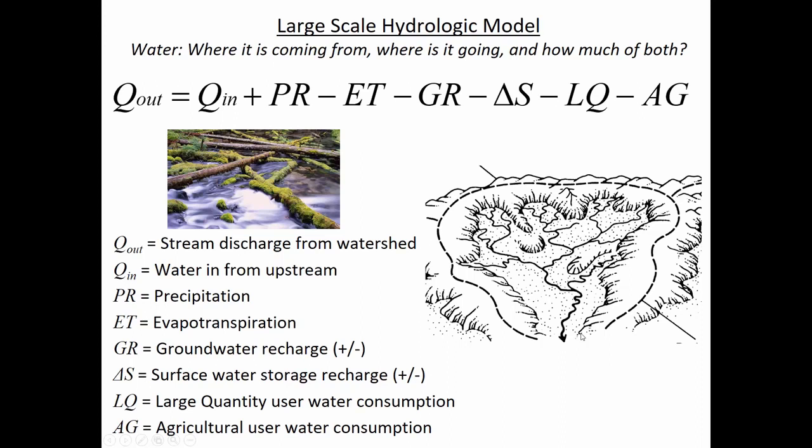So for this basin, just think about the river where water is coming out of a basin. Now, some watersheds have inflows to them, which means there may be a river that's coming into a watershed. So this image is showing that the watershed in question just is bounded by a ridgeline on all sides. And so this illustration wouldn't necessarily have a surface stream coming in, but sometimes we define watersheds so that there is a stream coming in. So of course, if we wanted to find the flow rate out, you'd have to account for the flow rate that was coming in.